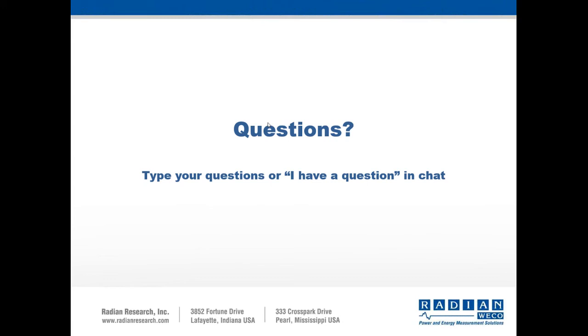So you can use the test board to energize the meter, get it powered up, and then use the built-in optic coupler on the test board to connect up to the meter and communicate through it that way. But in terms of how to do that, that's probably where I would look at talking with your specific meter manufacturer and their software on how to talk to the meter and program it that way.